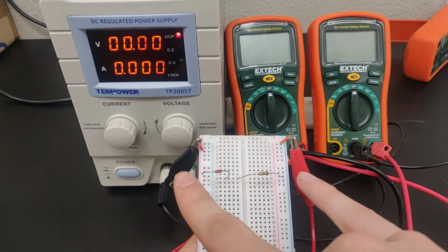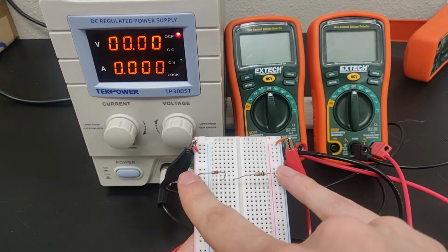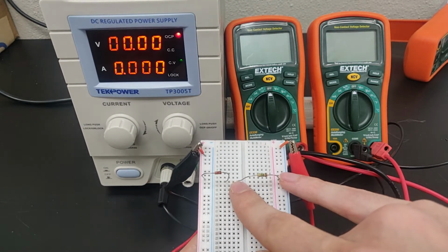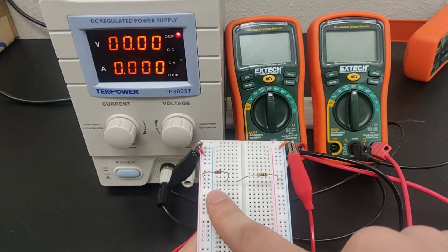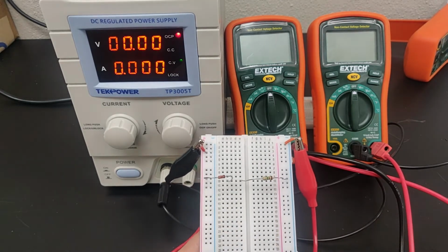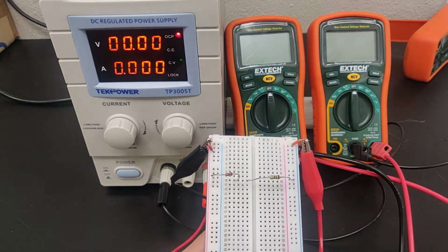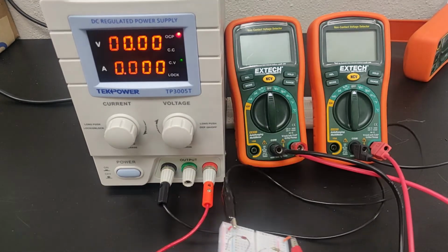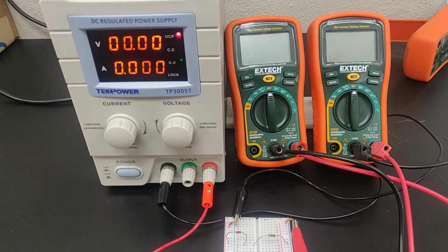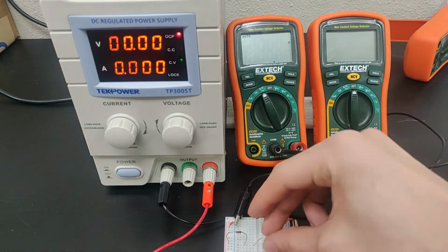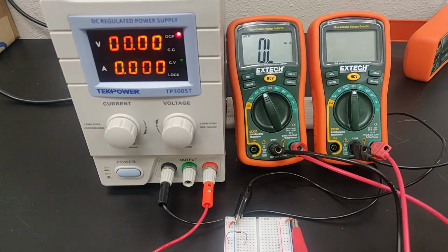So we can take the voltage drop over this whole circuit minus the voltage drop over our resistor, and that should give us the voltage drop over our diode, because again, this is going to be very small leading up to that full breakdown point. We can start by measuring the resistance of our mega ohm resistor, attaching our leads, and then we can start with this round of measurements. So for our mega ohm resistor,